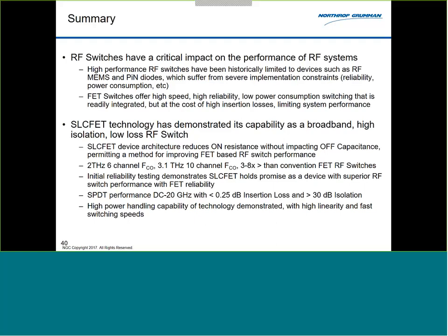Follow up on that: although your vacuum goes to nitride, you cannot avoid lateral oxidation of the nitride. So the question is, what about incidental oxidation of the AlGaN layers or the gallium nitride layers? I will say that.